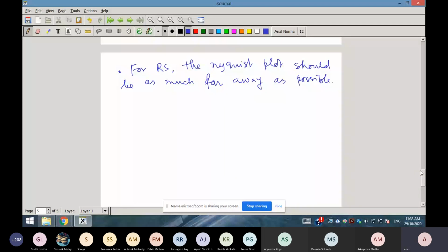Now let us define, and this definition is very important: Ms equals max over omega of mod S j omega. So Ms is the peak value of mod S j omega, the peak value of the Bode plot of the sensitivity function.